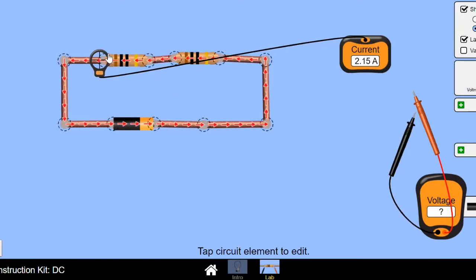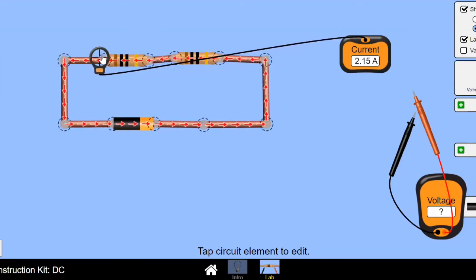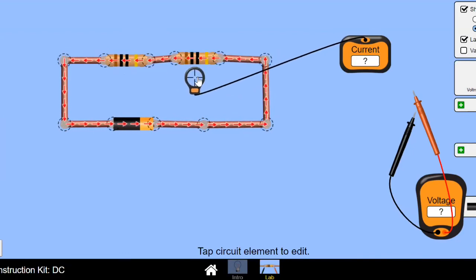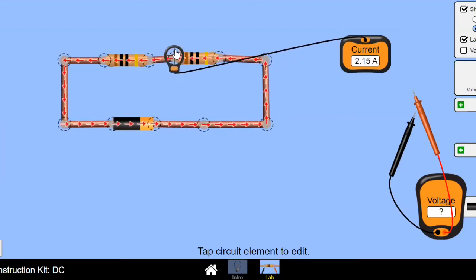And also I can see, if I look at resistor number 2, I going in 2.15, that is positive. So I going out also is 2.15, but definitely it should be negative. So the sum of them is equal 0. That is something that we expect from Kirchhoff's current law. The same thing is happening here. Current going through resistor number 1, 2.15, that is positive. Leaving is 2.15, that we consider as negative. Again, the total is equal 0.